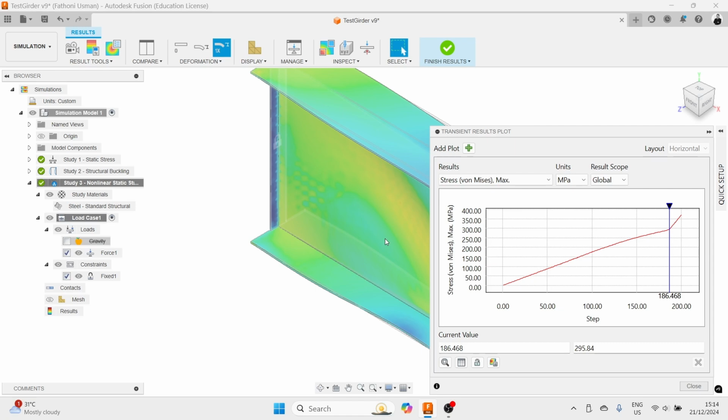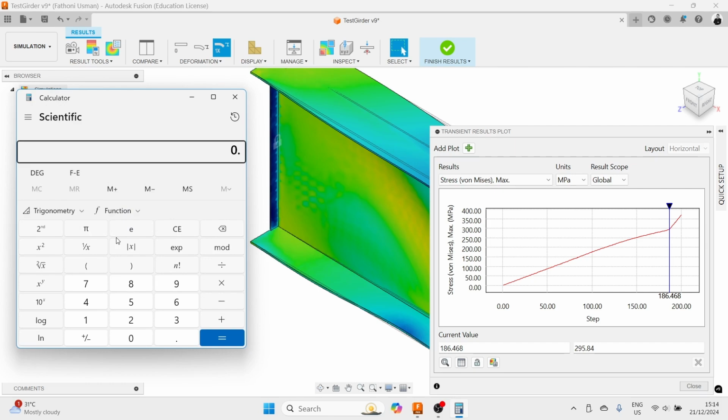So that's why it's slightly different. If we multiply 0.6 times 275, it is 165 for the buckling. The yield is reached when the buckling occurs, and here it is 186. So basically the design is quite underestimating. It is supposed to be able to reach more and have more strength, but anyway, it is because of the different materials.